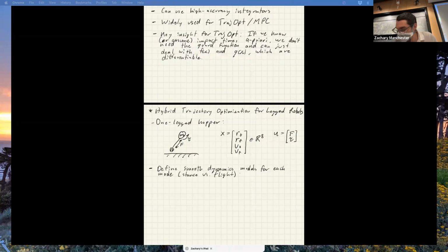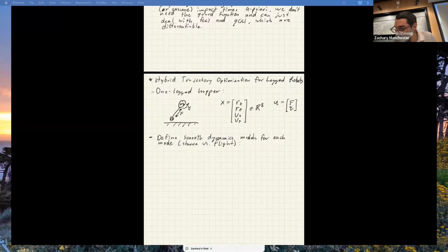Okay, so if I write both of those down, we're going to call the first one F1. And this is going to be our stance. Effectively what you're really doing here is sticking a pin joint between the foot and the ground. And again, I'm assuming no slip, right? So if you were trying to be legit about this and not have the robot face plant, you would then want to add some extra conditions on the tangential force at the foot to make sure you're not violating the friction cone conditions. And then we'd have our flight phase dynamics, which are the ones we already kind of wrote down.